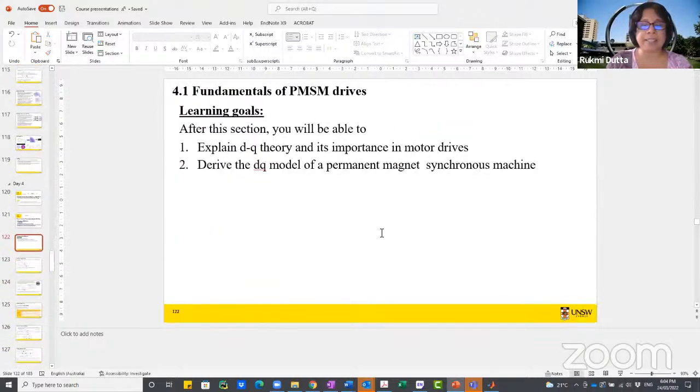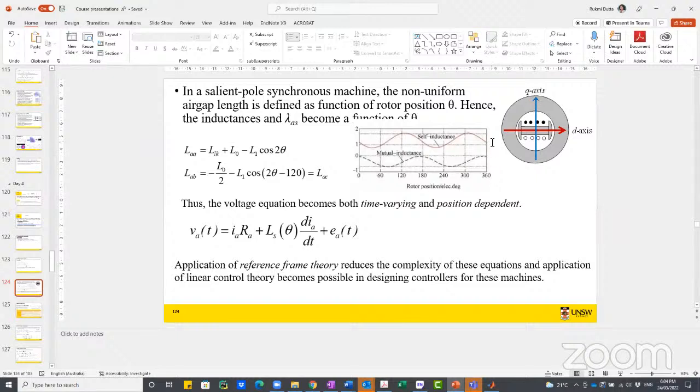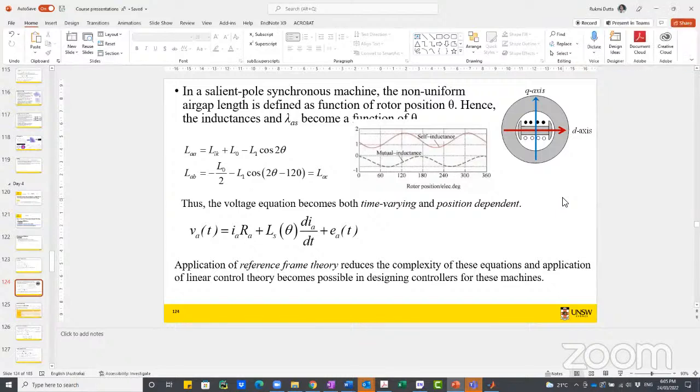So in the conventional machine, the d-axis has large Ld, whereas the q-axis has smaller inductance. But IPMSM is opposite, since in the d-axis the flux has to cross the magnet and then go to the air gap. So the magnet itself is like a big air gap. That's why the inductance of the d-axis is smaller. Okay. Thank you.